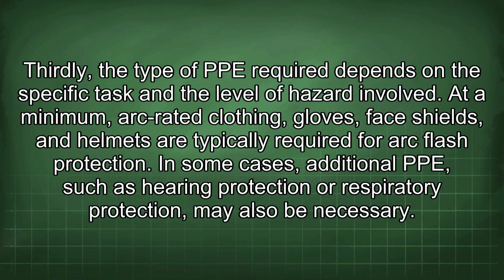Thirdly, the type of PPE required depends on the specific task and the level of hazard involved. At a minimum, arc-rated clothing, gloves, face shields, and helmets are typically required for arc flash protection. In some cases, additional PPE, such as hearing protection or respiratory protection, may also be necessary.